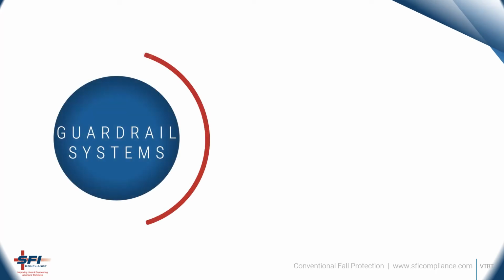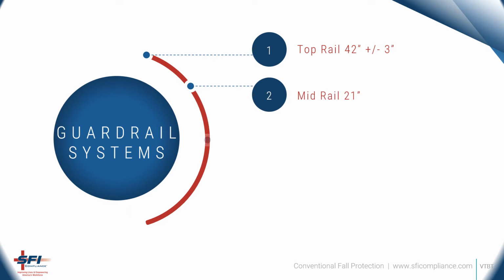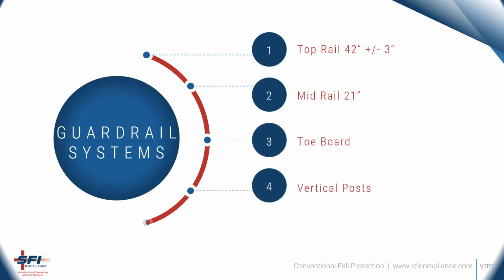Guardrails are one of the most effective ways to eliminate fall hazards and are a preferred method of fall protection. Floor openings into which an employee can accidentally trip on or walk into shall be guarded by standard railings with toe boards on all exposed sides. Wall openings from which there is a drop of over 6 feet shall be protected by standard guardrails as well.